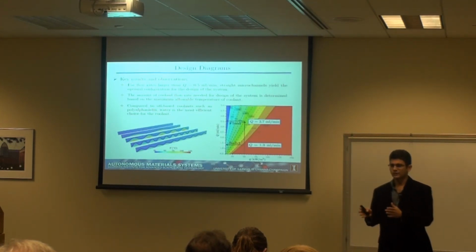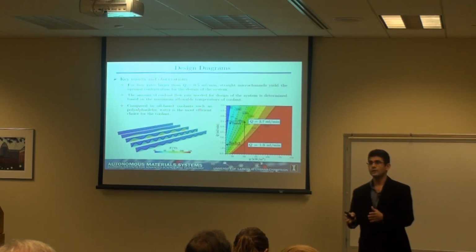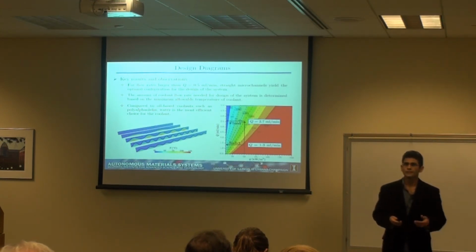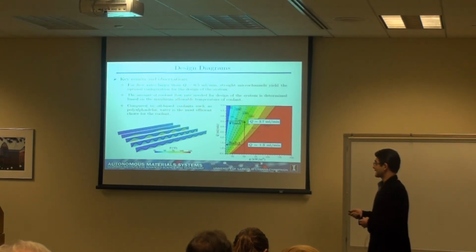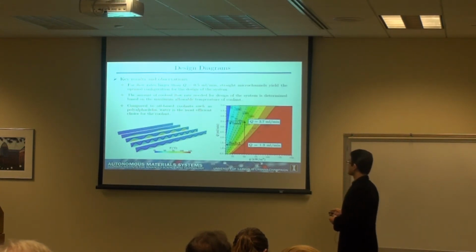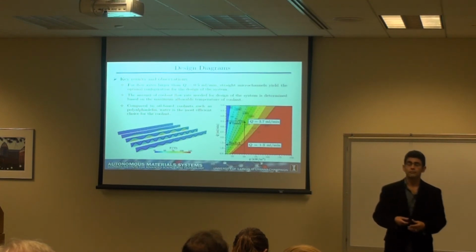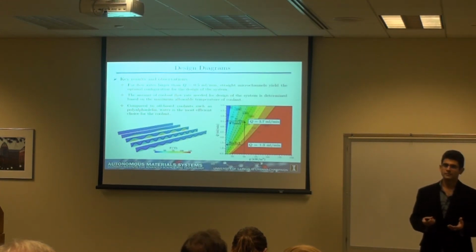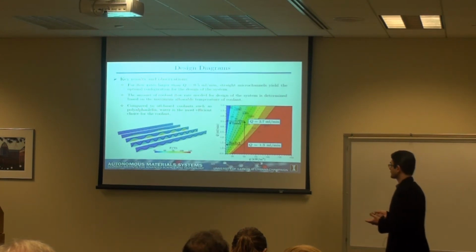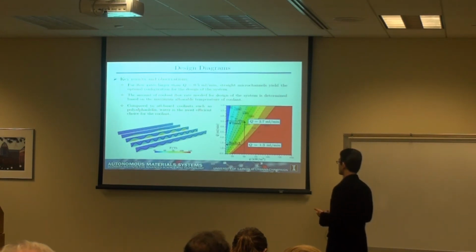So when we started this project, we said, okay, we look at water, then we look at better coolants like polyalphaolefin, which is commonly used in the aerospace industry. And again, it was quite surprising to see that water is actually a far better coolant compared to those coolants, especially because this is a composite material. We don't deal with corrosion here, so we can implement water for cooling.